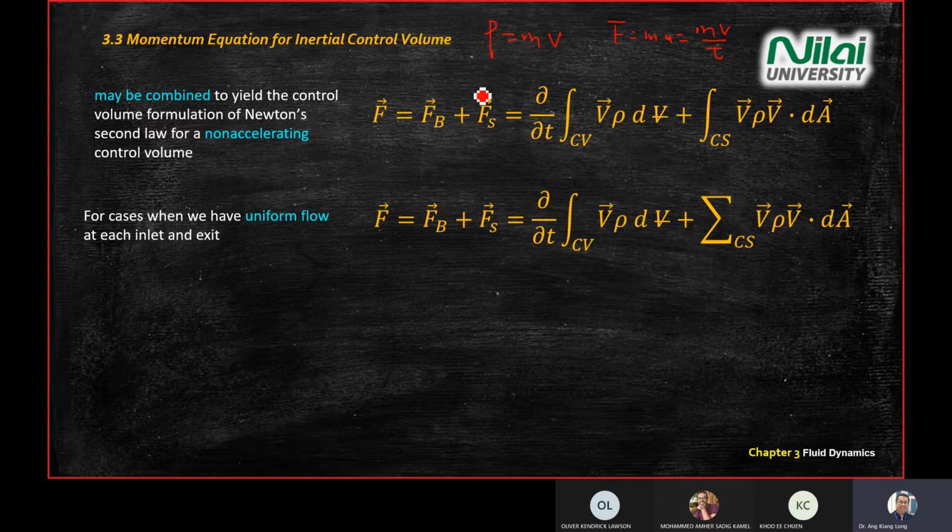And the momentum equation, you always start with the total force, so you need a free body diagram again. You draw all the forces with the free body diagram. You solve for the left-hand side, which consists of body force and surface force. What is related to body force again? It is related to mass and gravity. Surface force is what happens to the surface.